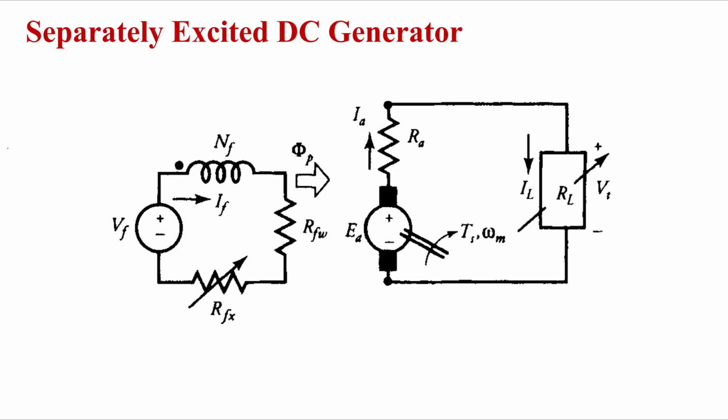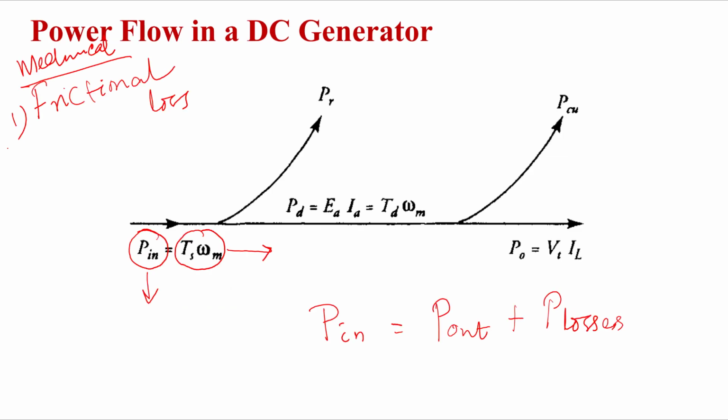What are the other losses, mechanical losses? One is the friction loss. Then there will be resistance to the wind inside the machine, because air is the fluid inside the machine, right? And when the machine rotates, there is an opposing resistance of the wind, and because of that also, some loss takes place. That is known as windage loss.